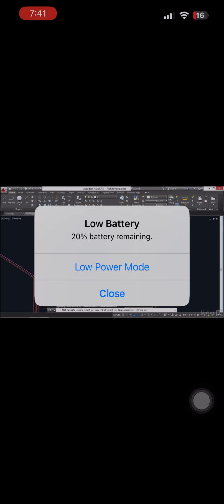so I can slide that horizontally. And now it looks like I need a little bit more room, so I will move this up and perhaps over a bit as well. And I will move this down and over. I'm able to do that quickly because I'm pressing the spacebar to repeat the move command. You can just press spacebar, move this from point A to point B, press the spacebar to repeat move that from point A to point B.